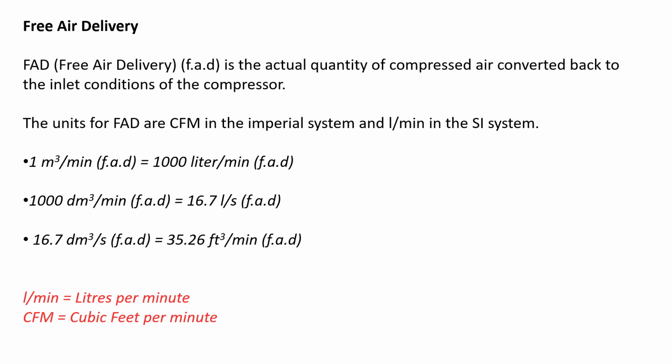There are many terms and units associated with compressor units. One of the main terms that you'll need to be familiar with is the FAD, or the free air delivery rating for the particular compressor unit. This is usually quoted in litres per minute for SI units or metric units, or CFM, or cubic feet per minute, for the inches system.